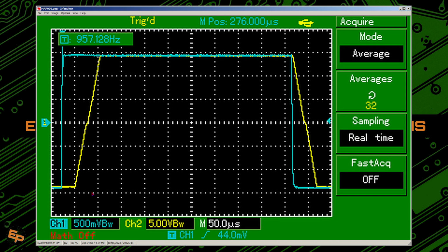And this is where we get to see this effect of saturation, because here when the input signal rises from the minimum value to the maximum value, we see that instead of the output voltage starting to rise slowly, just like in the previous case, the output voltage remains at that minimum value for some 30 microseconds. So it's basically like a delay, and then it starts to increase up until it gets to the maximum value.